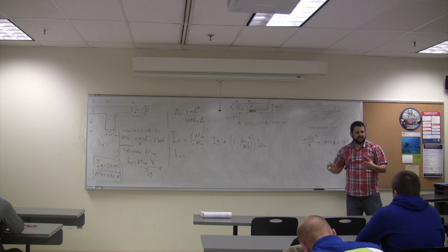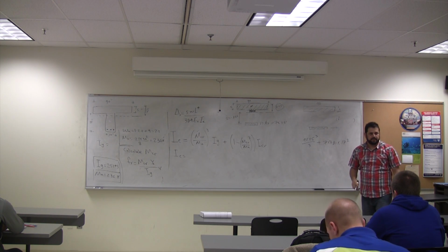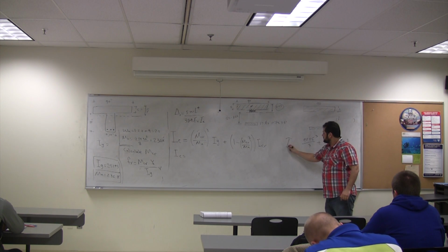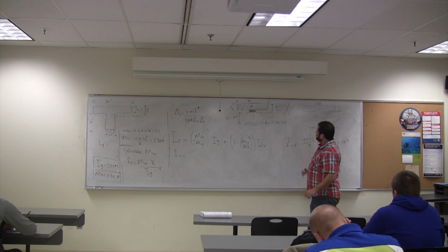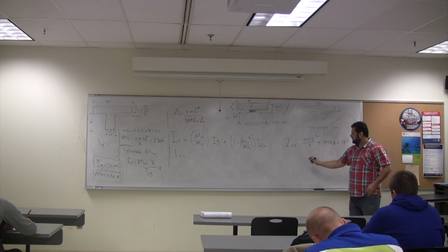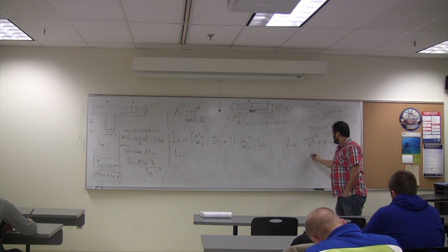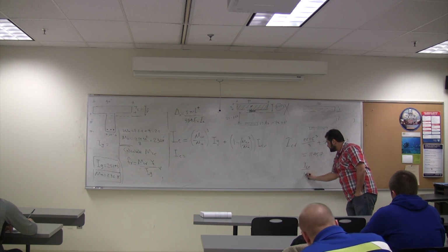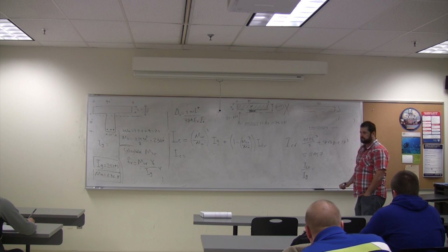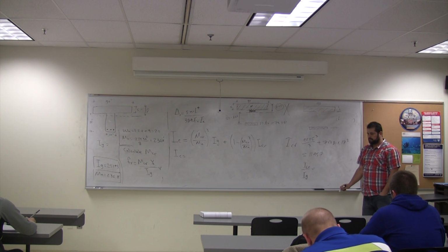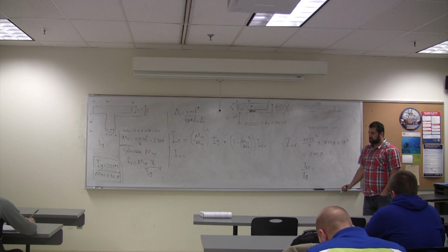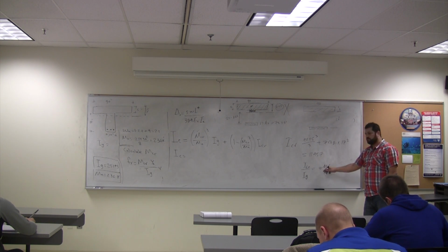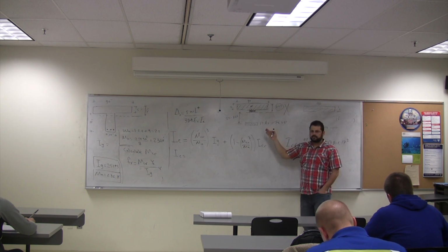Usually, guys, the cracked section is half of the gross area. Half. So what's I cracked in this case? Cannot be analyzed that way. How much? Again. 11,457. Yep, 11,457. And you can tell I crack over I gross is how much? 0.456. See? 0.45.